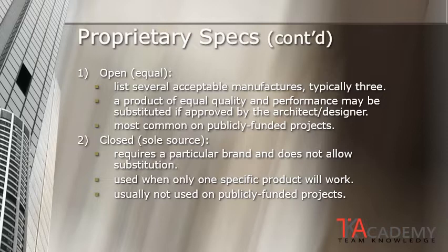It does not allow for competition. And that is the downside of using a closed or sole source. It is a very easy spec to write, but you do not get competition, and therefore you are usually subject to the highest price on your bid. That is the reason why it's typically not used on publicly funded projects. A sole source is more common on private projects.